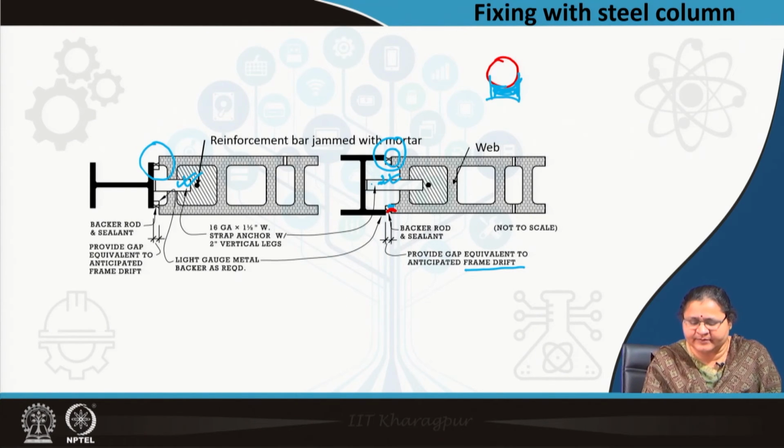This steel strap is bolted on this face, and on the other side it is embedded in the concrete. This is mortar, and you can see the rod reinforcement which is keeping it stable and continuous. All the blocks here are tied by this rod, one after the other.